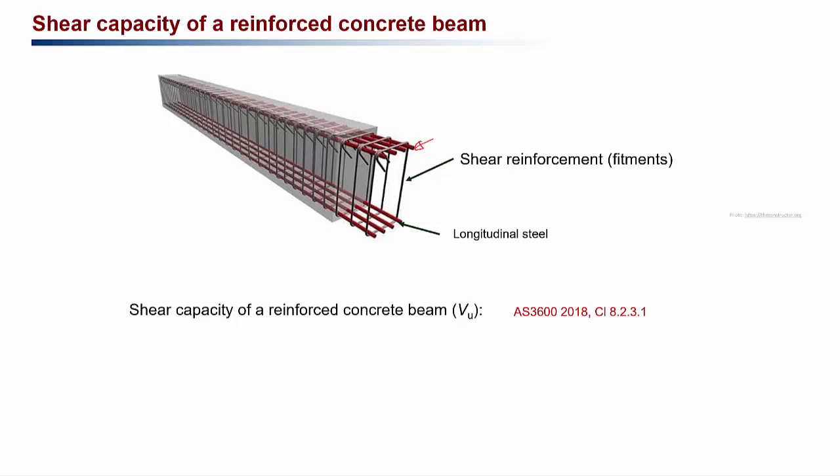But apart from these longitudinal reinforcements, we see the transverse reinforcement as well, and they are called the shear reinforcement. As you can see here, these are the shear reinforcements, or they are called fitments or transverse reinforcement or web reinforcement as well. So these reinforcements are there to take the shear stresses due to the shear force.